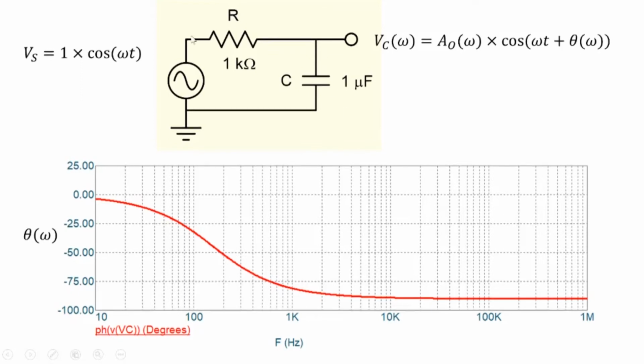So the signal that comes out initially for very low frequencies, the phase is very close to 0. So, as we said, the circuit is transparent to low frequency signals. The signal that you apply here just appears over here. But as the frequency increases, the amplitude also decreases, and the phase also starts getting different here. The phase starts becoming negative here.